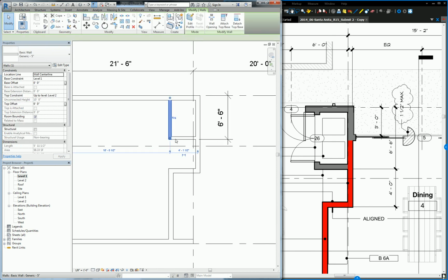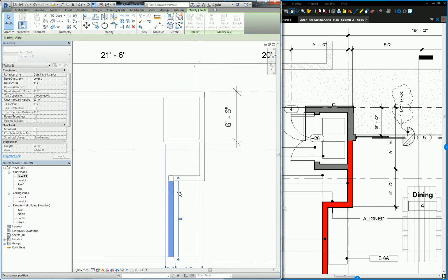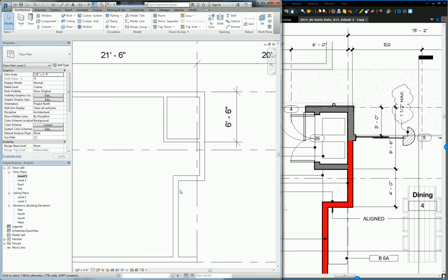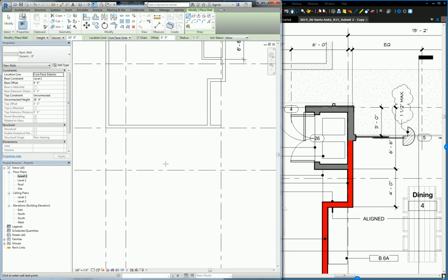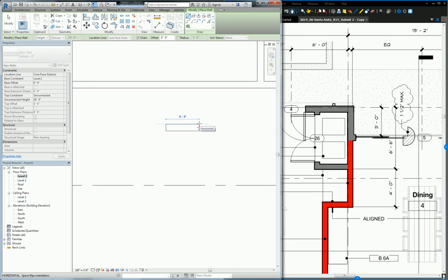No, oh no, it's actually sticking out a little further. I didn't ask my question properly. Yeah. So when we started, we have the wall flush with the grid line. Mm-hmm. So when we turn, is that wall thinking it's still flush with some grid line? Yes, so I'll go over here. It doesn't have to be flush with a grid line. It's just wherever I put my mouse. See how it's on the inside of my mouse line? Oh, I got you. All right. So if I click down and it goes that way, then it's going to connect that corner there. Does that make sense? And you can flip it too with the space bar.